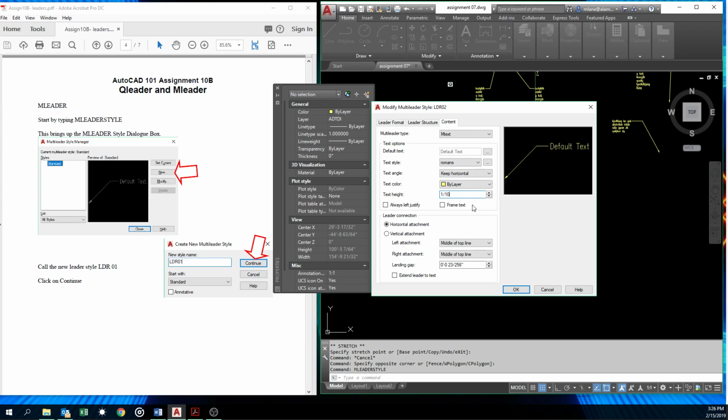With CAD, since we're scaling things up and down using a factor of 10, instead of trying to remember these weird numbers of how big is my text on a 1/8 inch equals a foot drawing, so it's 8 times 12, 96, that means that we don't have to remember that. We know it's 1 to 96, because remember 1/8 inch per foot, there's 8/8 of an inch in an inch, 12 inches in a foot, so 8 times 12, 96.